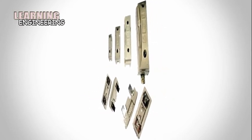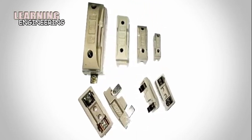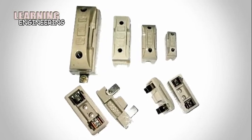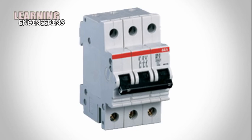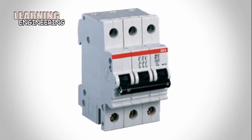There are some self-resetting fuses that will heal after a certain amount of time. These are called PTC fuses and have a high resistance state when hot. If the heat was caused by overcurrent, then removing the overload will restore the fuse to operation mode. On the other hand, a circuit breaker is a multiple-use device.